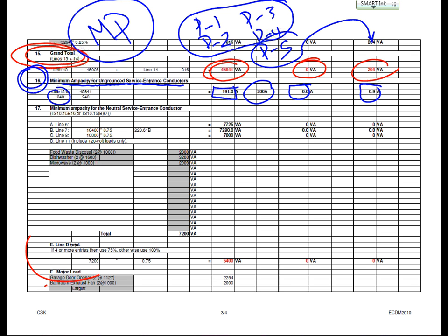I came up with a 100, say 100 or 125 amp panel, single phase 240, 60 hertz. That's going to be protected by a 125 amp circuit breaker, with four conductors, number 4, landing on it. Done. That's the sizing for each and every one of these apartments. Again, all four of them are the same.